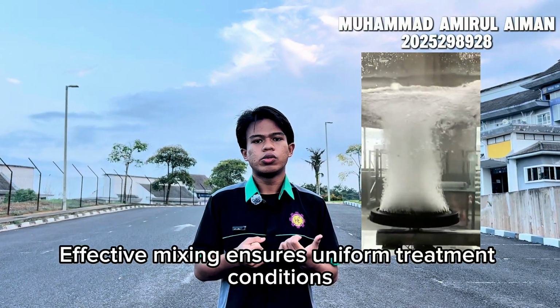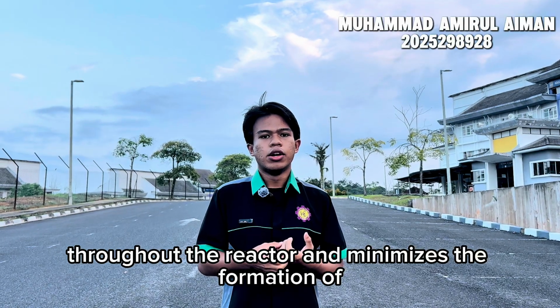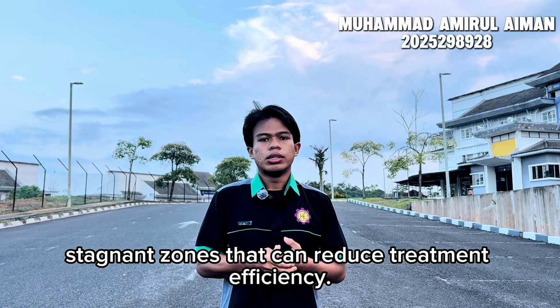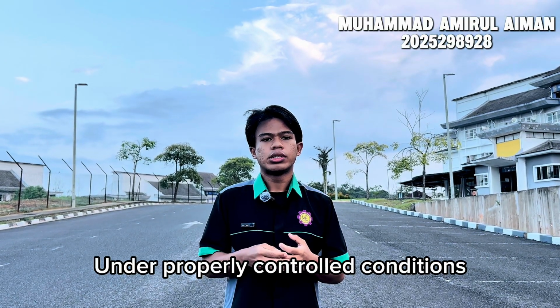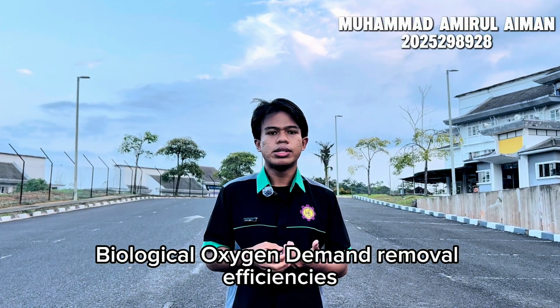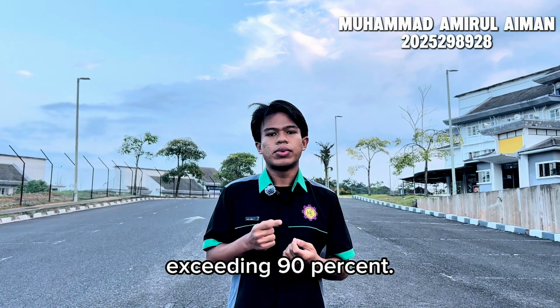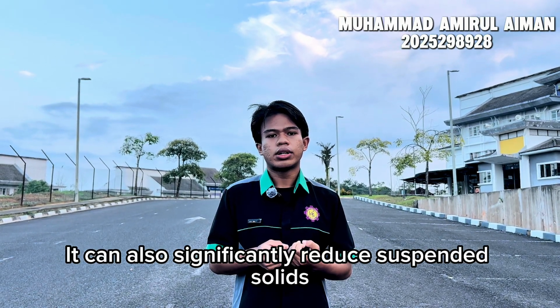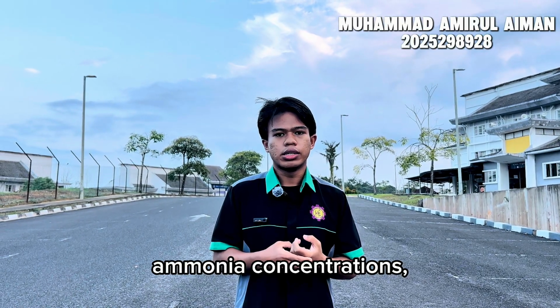Effective mixing ensures uniform treatment conditions throughout the reactor and minimizes the formation of stagnant zones, which can reduce the treatment efficiency. So, under proper control conditions, the activated sludge process can achieve biological oxygen demand removal efficiency exceeding 90%, and it can also significantly reduce suspended solids and ammonia concentration.